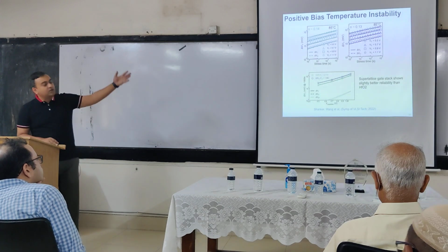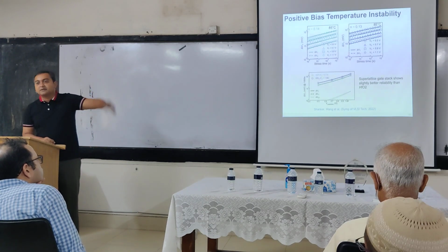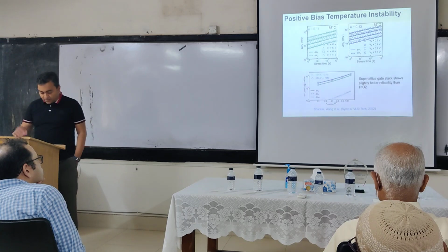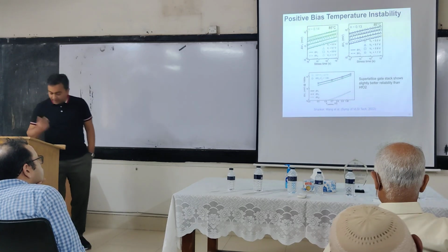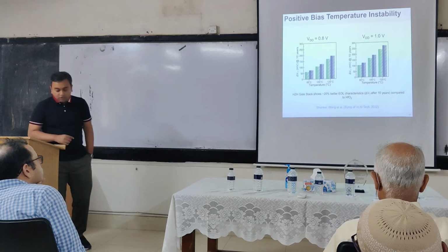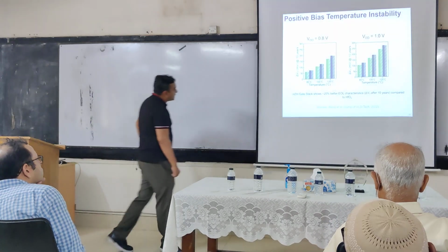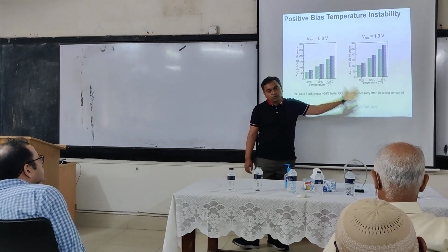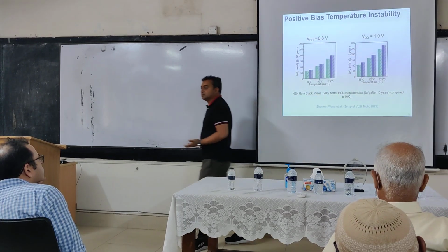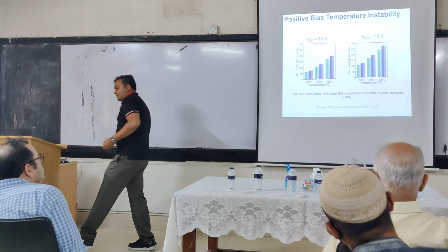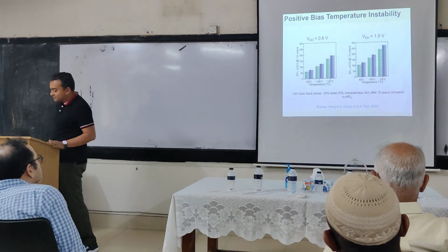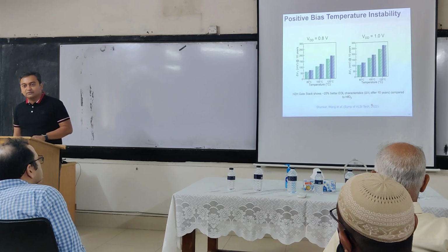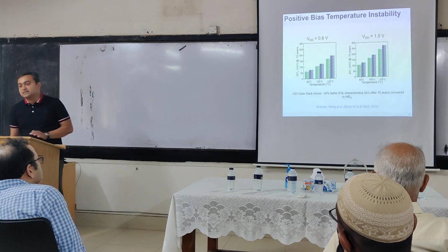So anytime we talk about a new gate oxide, like negative capacitance gate oxide, we have to do measurements. So that's what we do. And again, long story short, compared to hafnium dioxide, we actually see better reliability at all voltages and all temperatures. So again, this is also a very new result. This is from 1 month ago that we presented and realized the program.